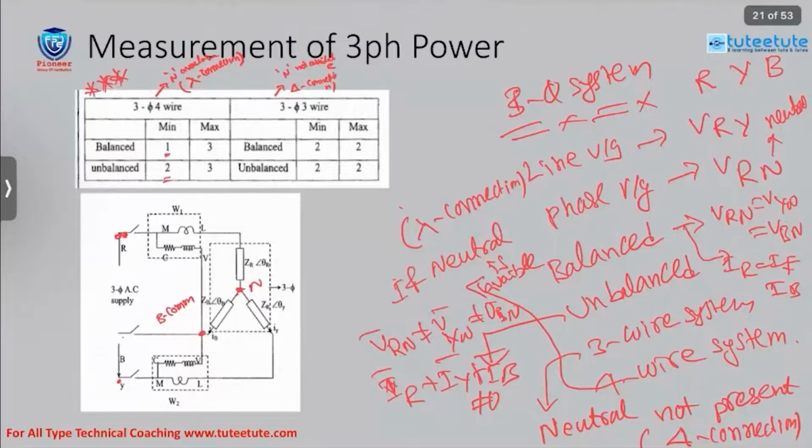but the balanced condition should be there. Balanced, yeah, then it is okay. Okay, sir. Kumar sir told that in a previous year question, they asked like this. That means if they didn't mention anything, we need to consider it as unbalanced. If they specifically mention a three-phase balanced system, then the minimum number of wattmeters required is one.